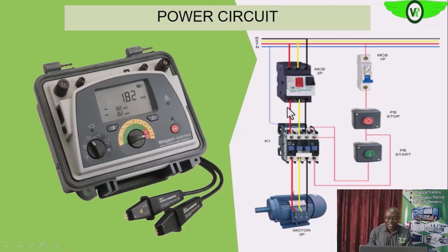We know that if there is resistance build up along any of these lines, it can cause voltage unbalance. And as we saw earlier, that voltage unbalance has the effect of increasing the current that is flowing through the system, and thus the heat that is dissipated in our electric motor.